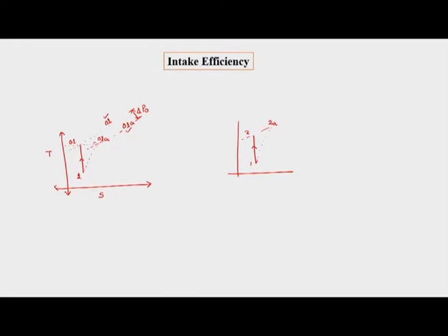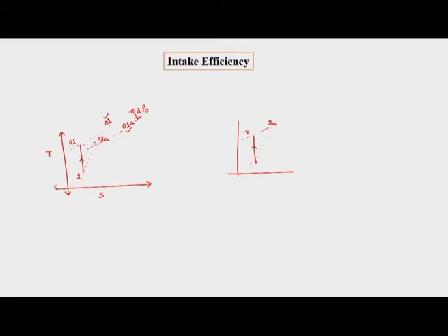So, a shock, which leads to a sudden rise in pressure, is a non-isentropic process. So, we have greater loss in total pressure in the intake in case of scramjet and ramjet intakes. So, the design of scramjet and ramjet intakes is a more challenging task than in case of subsonic intakes.